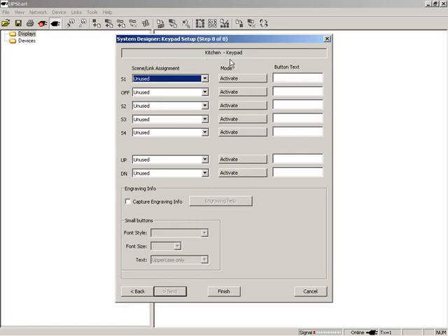Now, it's also said I've got a keypad in the kitchen. So S1 is the Scene 1 button here at the top. Let me kind of zoom in on that to give those that haven't really seen this keypad just yet. We have Scene 1, 2, 3, 4, and off, and then we have a bright and dim button. Now, the nice thing about this keypad is that all 7 of these buttons can actually be programmed, and there is LED tracking. So I could actually make this up and down button my all on or my all off instead of being a bright or a dim, and I can actually track the LED on that.